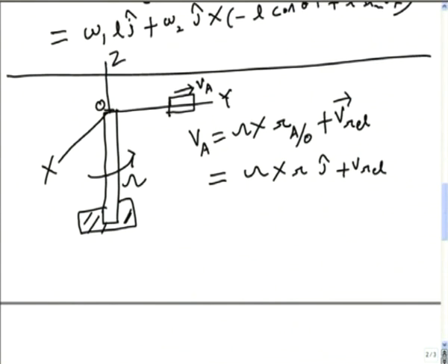And this one, the absolute acceleration, will be omega square r j plus twice omega v rel i, where 2 omega v rel is the Coriolis acceleration, and that is what happens. So these equations which we discussed can be used for 3-dimensional things also.